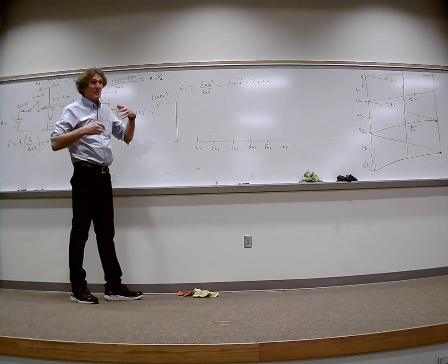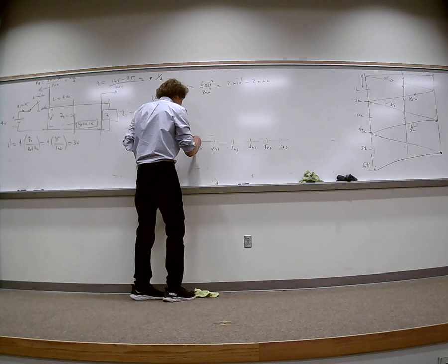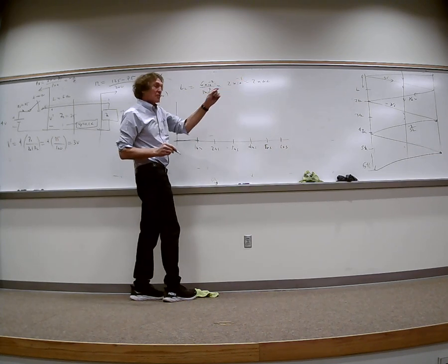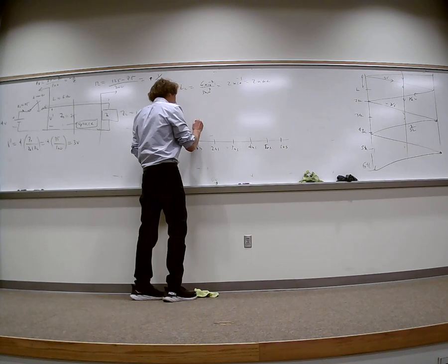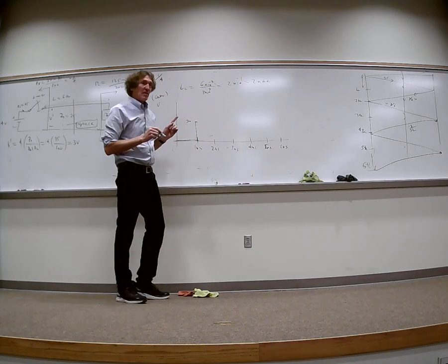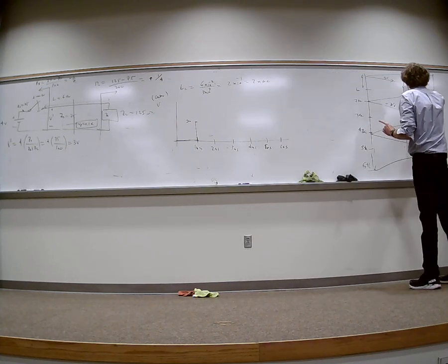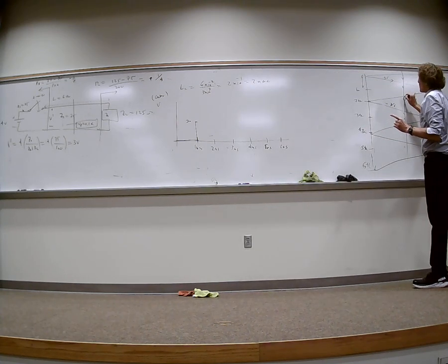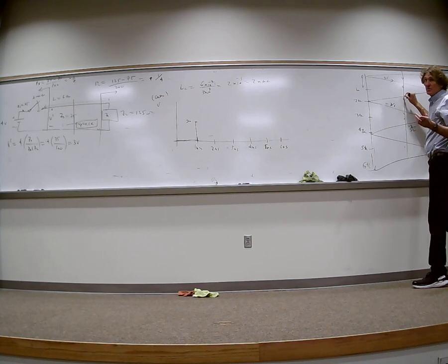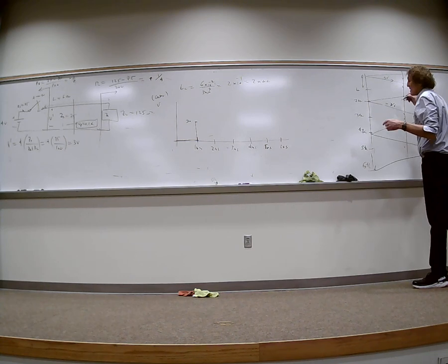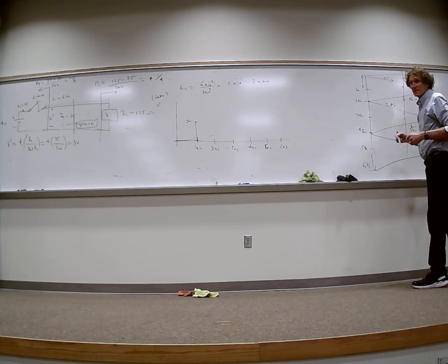Y'all with me? So no voltage at all until it hits 1 nanosecond. Then it's going to go up to, y'all see it? 3 volts, right? And it's going to stay there for how long? Well, here and then here. So a full 2 nanoseconds, right? Because this is basically halfway down, halfway down. It's a full time constant of 2 nanoseconds.